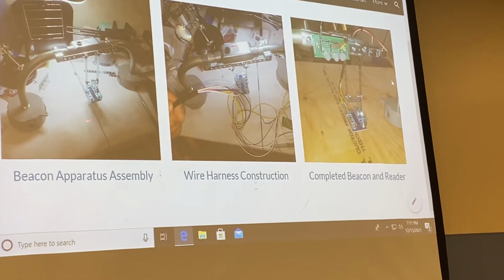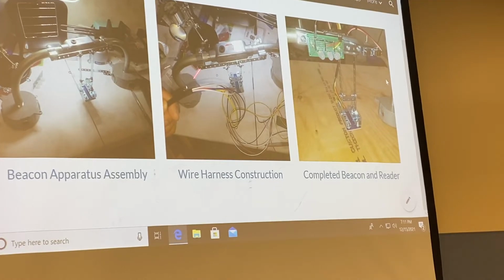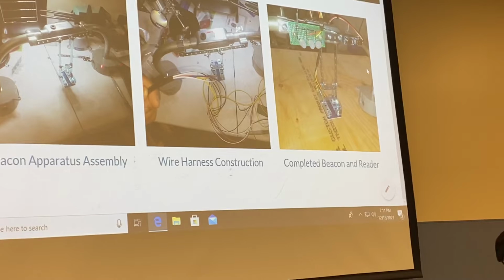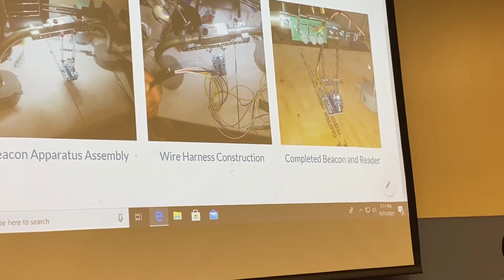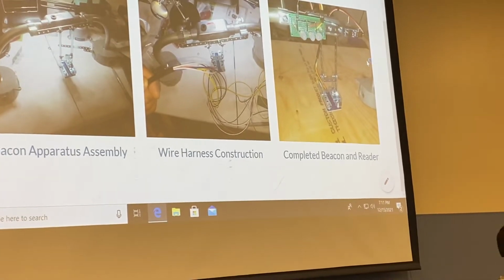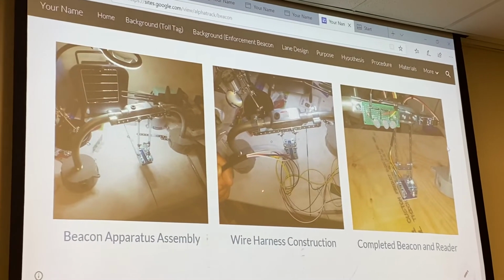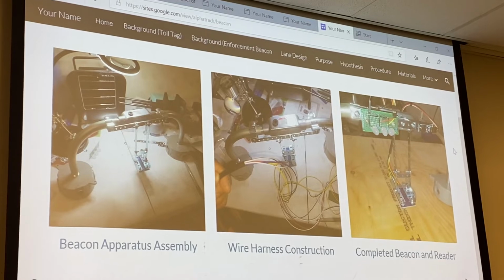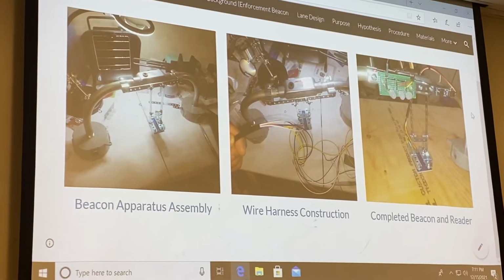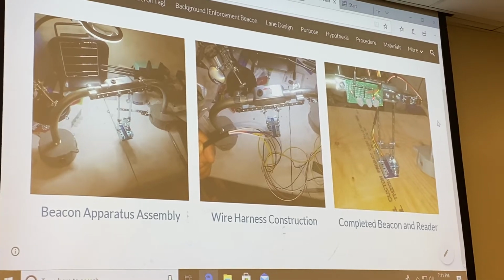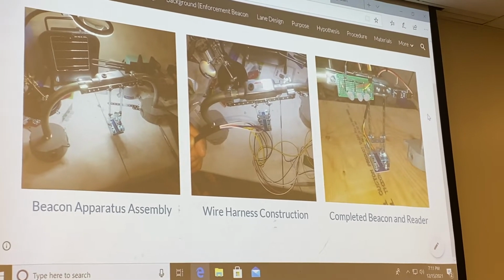So got that. We had to make our own custom wire harness, and we had to terminate each wire. After that, we pulled everything through over here and ran them to the appropriate modules. And basically that's our finished product over here. So we got wires running through here into the junction box, and we got 3 outlets, one coming to the beacon, one coming to the buzzer, and one coming to the RFID sensor.